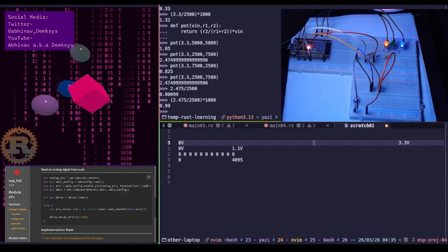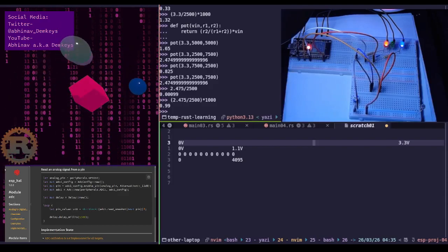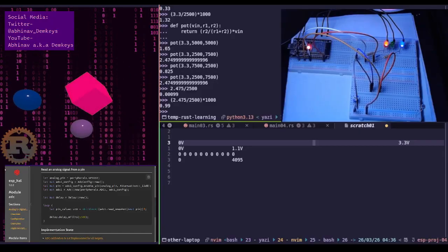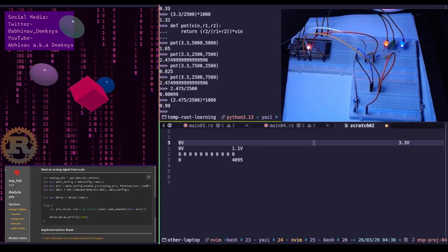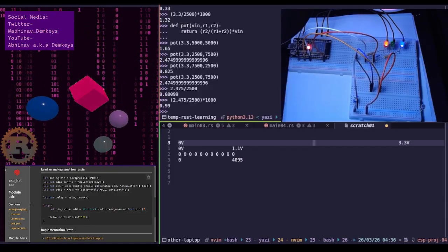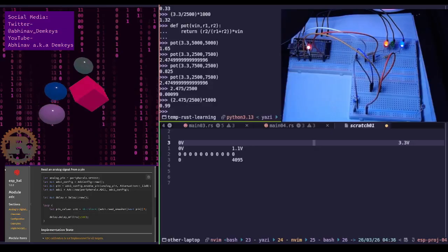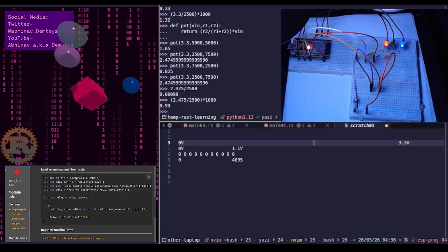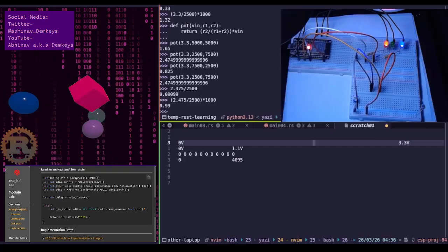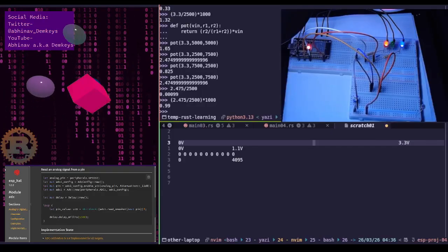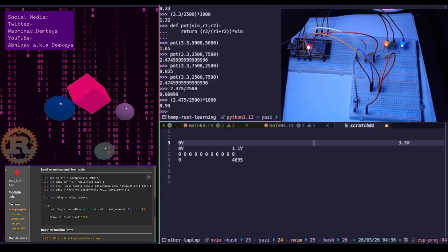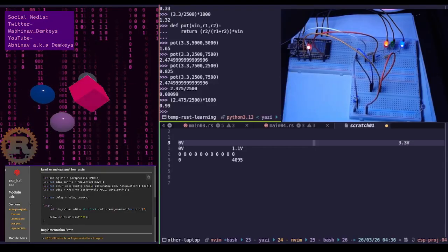Actually, I wasn't able to put that into words for some reason. This thing about the pot touching 1.1 volt, I wasn't able to explain that that's what I was talking about. That's why I had to draw out the entire scale. Okay, the remaining two-thirds of your knob's rotation will just return the same maximum value. It's like trying to measure a 6-foot person with a 2-foot ruler.